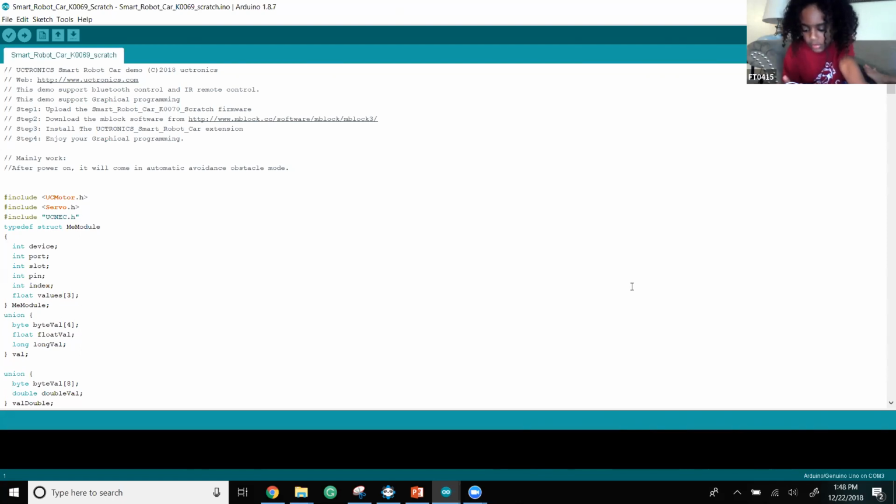You can see that on your sensor, your sonar, which shows that type of thing. It has dot, dot, dot on one side and dash, dash, dash on the far right on the other side. And it goes into the board and it says GND on one side and VCC on the other side. So make sure they line up.